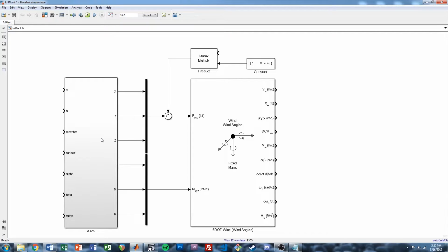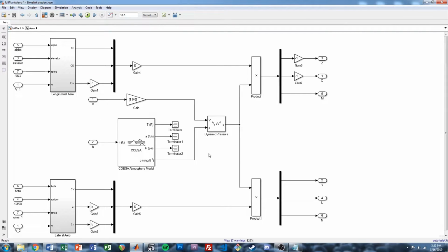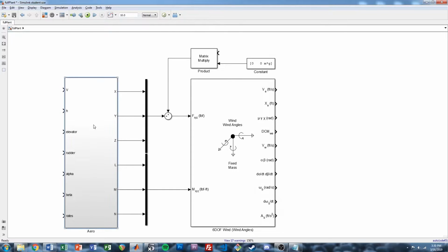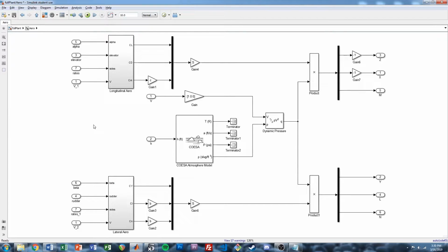And one thing that we're not quite doing exactly right here is, since the force inputs are expected to be in the wind axes, and we're using CY, that's in the stability axes. We'd want to use the crosswind force to be a little bit more precise, but we're pretty much always operating around 0 beta, for the most part at least. So I think this will be okay. Do we want to do one more rotation? I think it'll be fine.